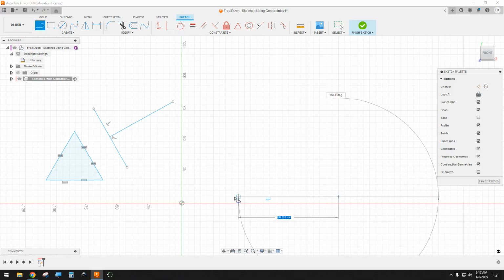What you'll notice is that Inventor, or sorry, Fusion 360, will sometimes decide and automatically put constraints. So if you had it like this in a straight line, you'll notice that there is a blue horizontal constraint popping up. And once you move it, that constraint goes away. So it kind of tries to think for you.